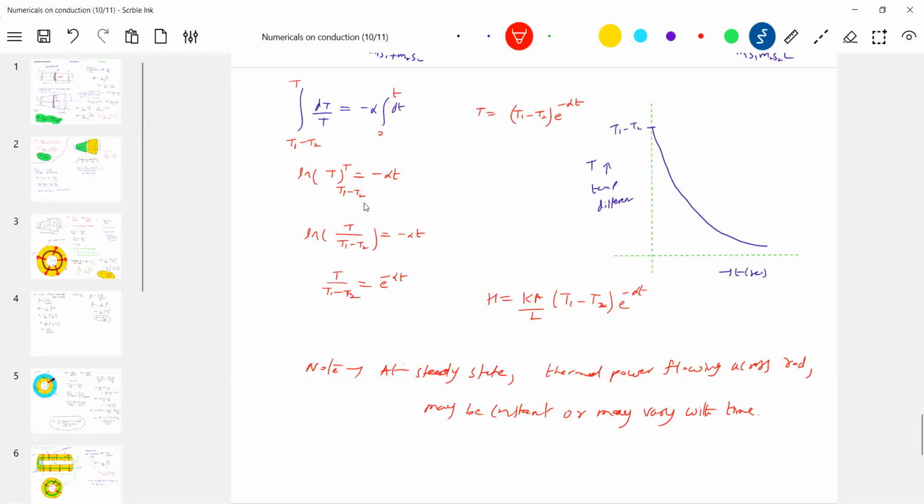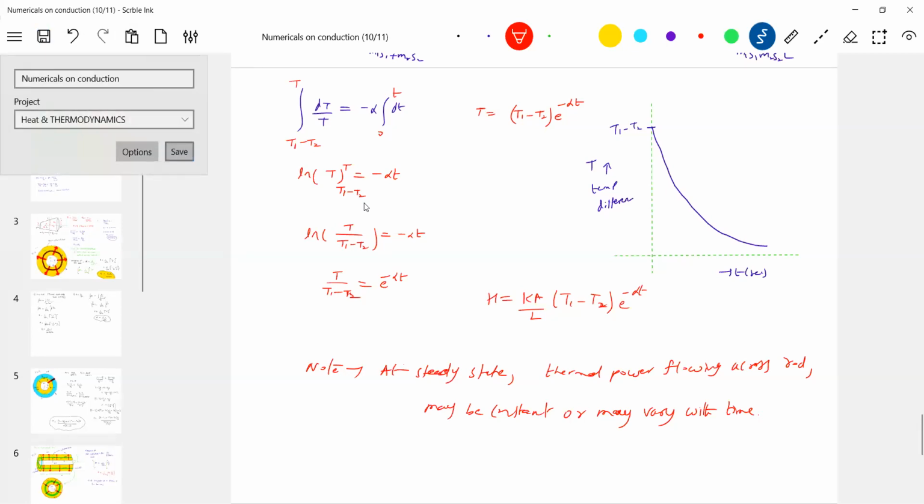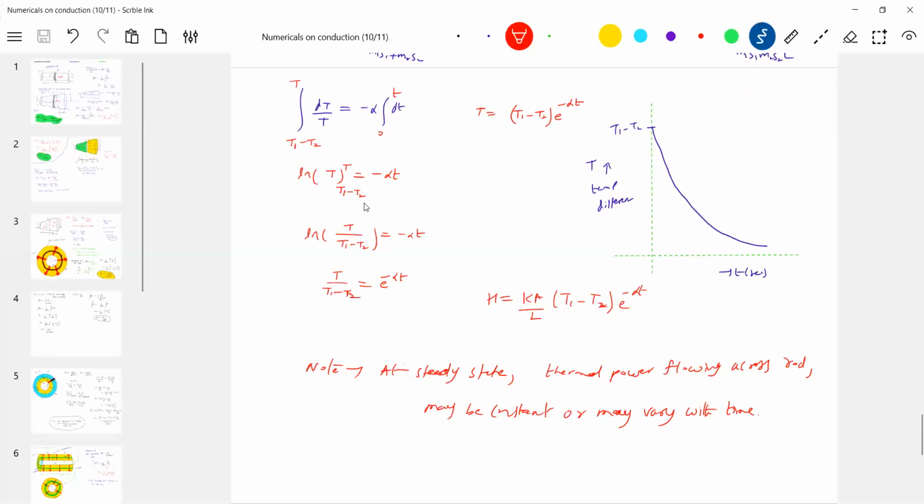Okay, agreed now? That's what this particular question is reflecting. Because the moment steady state is mentioned, most of us will think in the beginning, okay, H will be constant. We took numericals of that kind where H was constant. Here H is varying. So at t equals 0 or at any time t, no part of the rod will be involved in absorption of heat, only in the transfer of it. That's the meaning of steady state or thermally lagged. Even if you say the rod is thermally lagged, it is the same thing. You mean that condition only.